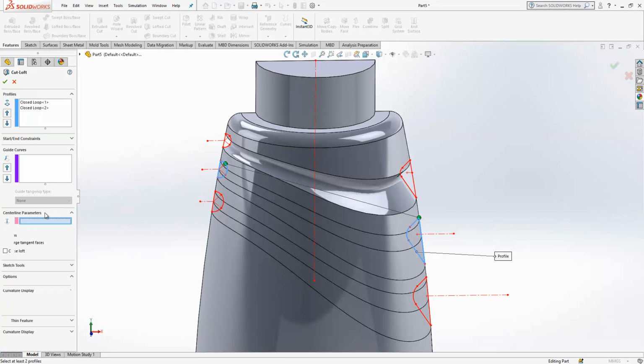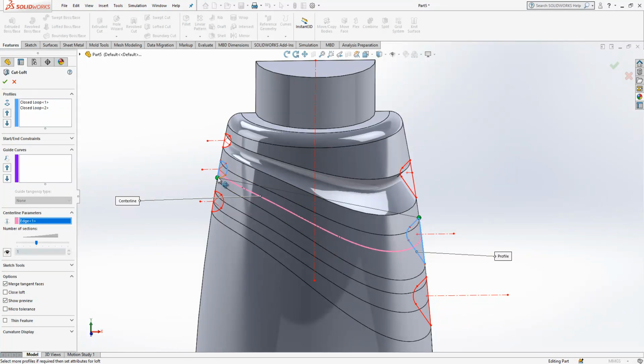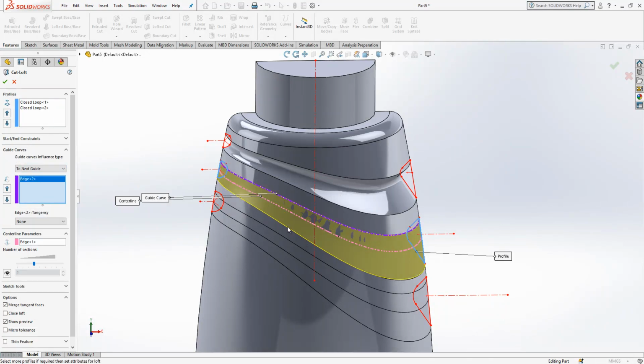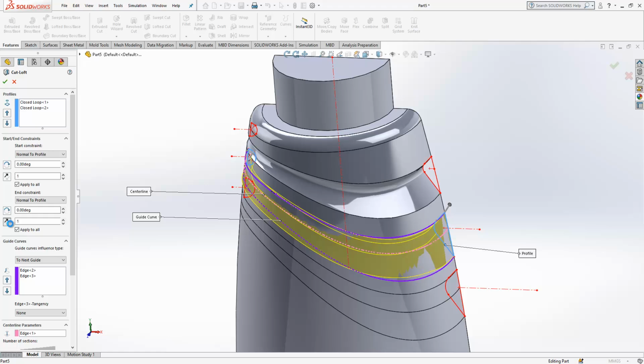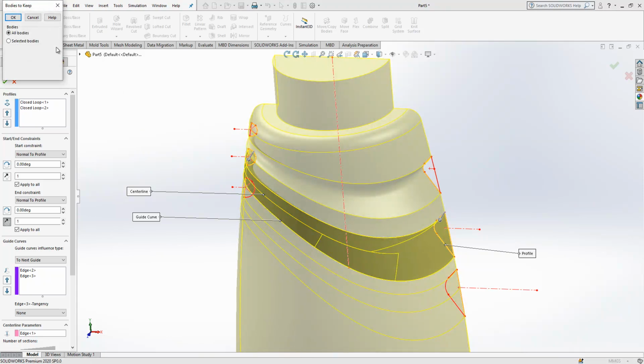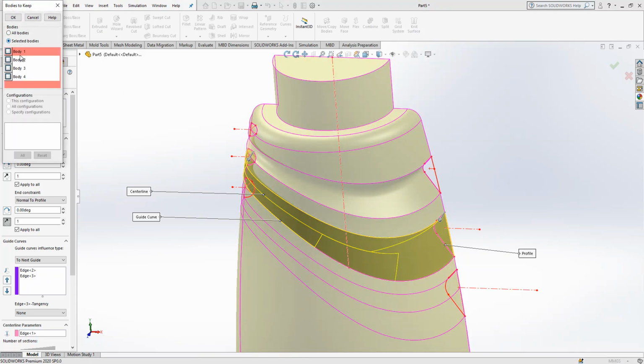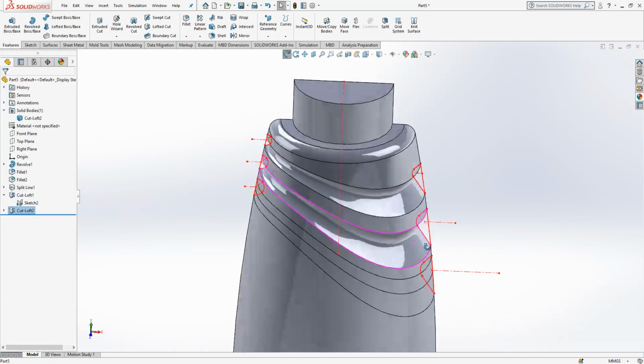They are looking good. Center line parameters, center line here, control point at the other side, the right edge, and we have this control edge, this control edge. Yeah, in fact, boundary conditions. And what we missed now: normal to profile and normal to profile. Arrows looking to the good side. Yes, now we should make it this side. And now it's okay. Apply. Same idea. Yes, we create microsurfaces. We don't care about them.